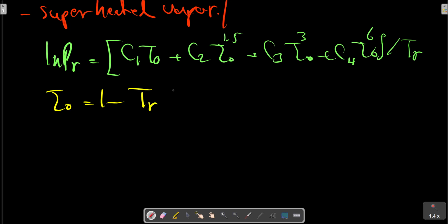The next step is to determine an equation of state for the vapor region that accurately represents the PVT data. It would be desirable to have an equation that is explicit in V in order to use P and T as the independent variables in calculating enthalpy and entropy change from the previous equations, respectively.